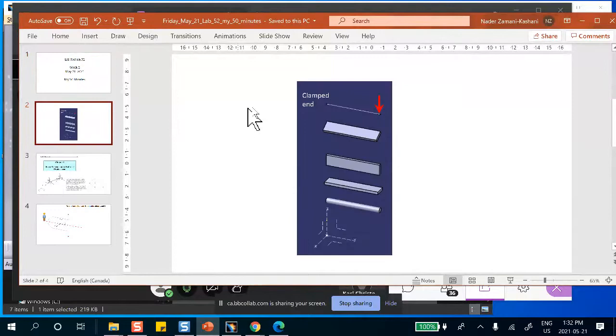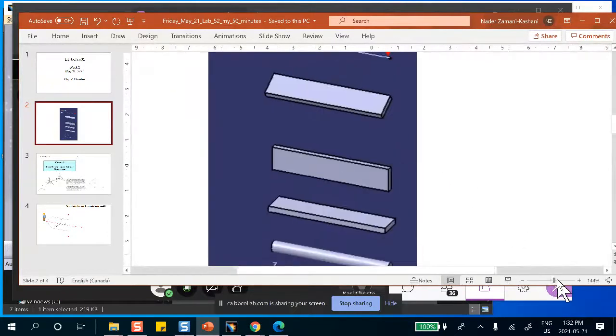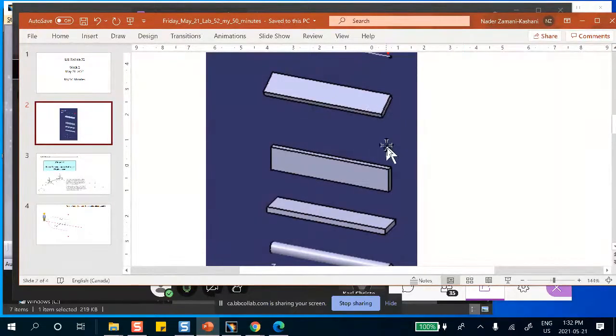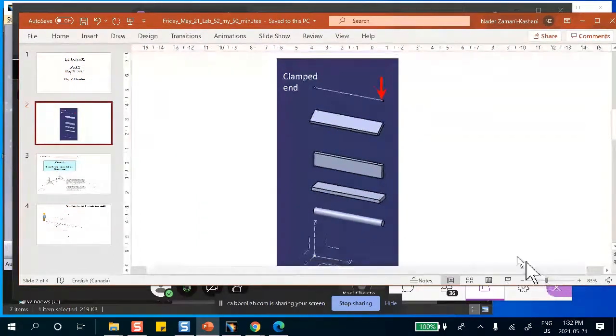Now, in the case of 3D beams that we are dealing with here, because the beams can be in 3D, that's not good enough, because you can draw a line and you can have a cross-section, for example, a rectangular shape like that, rectangular shape like that, or the same thing. The orientation of this cross-section also matters. The only time the orientation doesn't matter is when the beam has a circular cross-section.